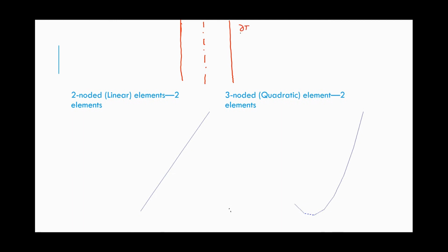So my governing equation is del T del t equal to alpha del squared T del z squared, where z is this dimension, and we have an initial temperature Ti, and then the surroundings are at T infinity.